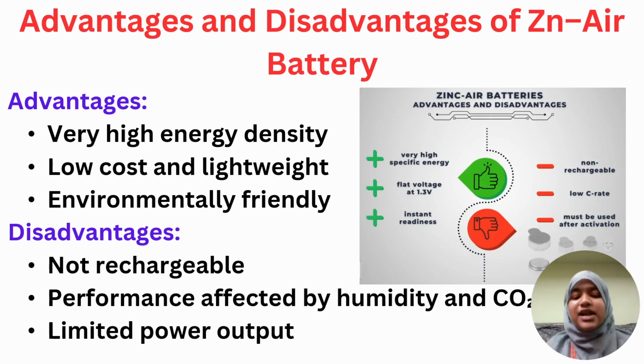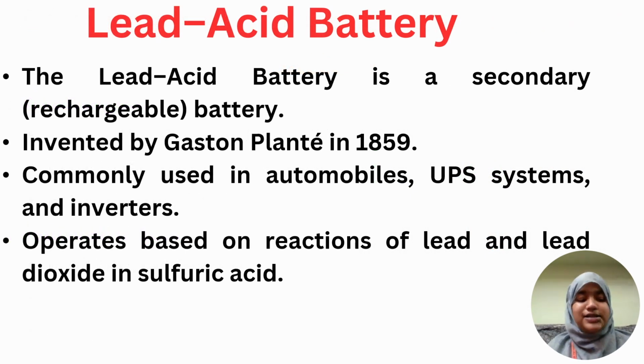And advantages and disadvantages of the zinc air battery. Advantages: it has very high energy density, it is very low cost, lightweight and environmentally friendly. If we come to disadvantages, it is not rechargeable, performance is affected by humidity and carbon dioxide, and it has limited power output.